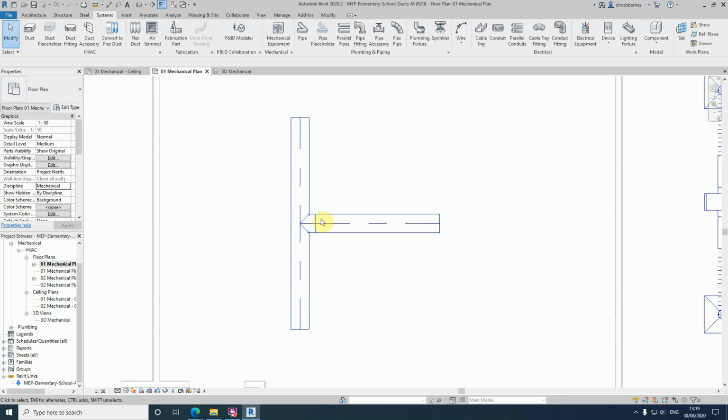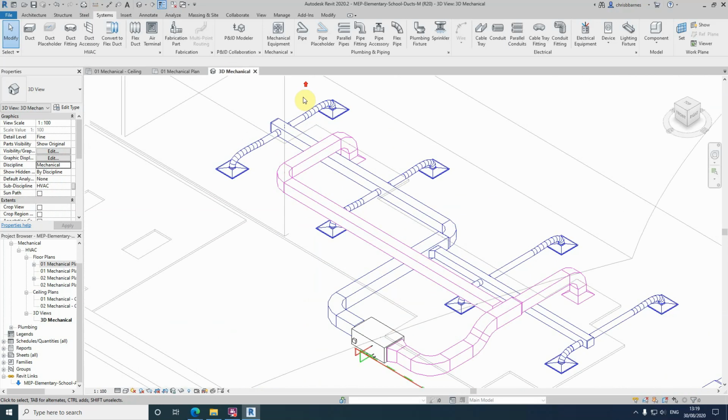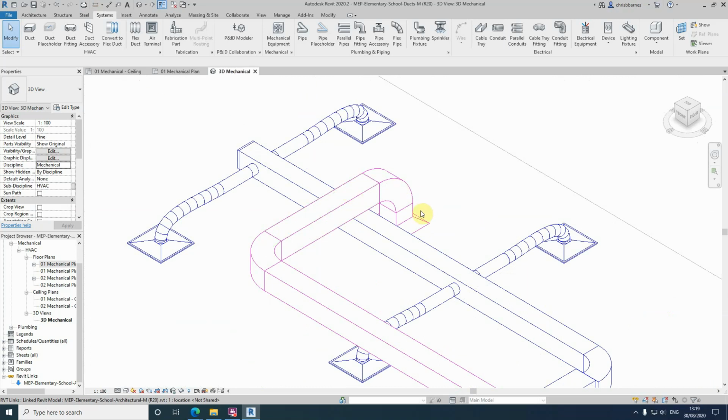Okay. Now another method of modifying is to convert rigid duct into Flexiduct. So let's look at an example here. So we've got our rigid duct going around and connecting into our return air grill in this instance. We've already done these. Now we wish to apply and change this piece of duct and put a flexible connection on here. So to do this, all we need to do is click on this convert to Flexiduct.